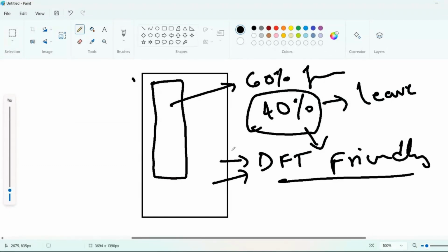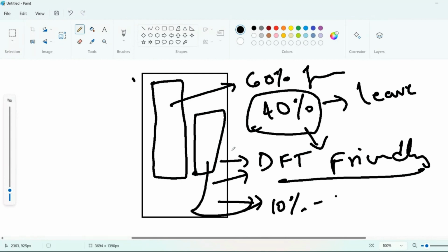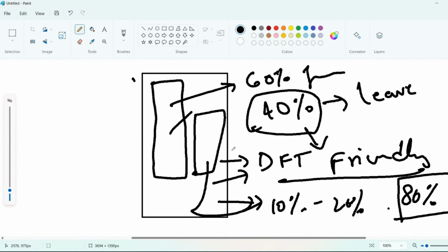Okay, then they give you a good amount of area for DFT logic. Let's say your DFT logic is added like 10% to 20% on top of your functional logic. So this is area overhead. So now it became how much? 60 plus 20 is 80% you are occupying. So there is only a narrow 20% area available, the free space available.